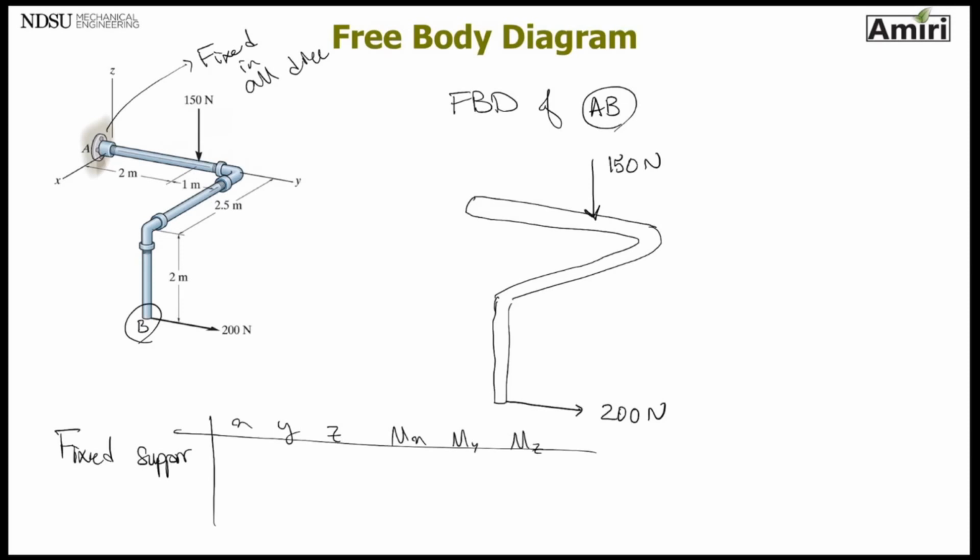I just told you that this does not move in any direction. It's 100% fixed in all directions. Does it move in X? Nope. Does it move in Y? Nope. Move in Z? Nope. Rotation about X-axis? I hope not. It's fixed. Rotation about Y? Nope. Rotation about Z? No. So we have 6 no's. We need to get to work and put 6 reactions, 3 forces and 3 moments there.